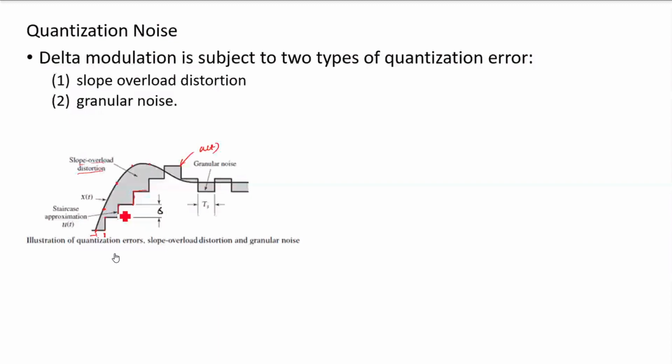Now, with this step size, if the same signal is stable for some time, there is a rise in the approximation, and then a fall, depending on the difference between the sample and the approximation. There is a rise, fall, and rise, with the approximation level much lower than the signal sample level. This results in loss of signal, which is nothing but granular noise.